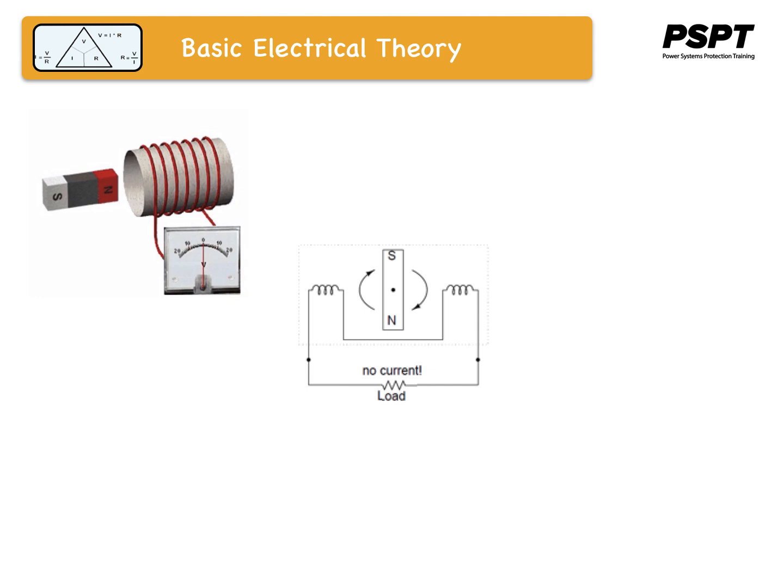If the magnet is in this position as it rotates, there's no current flowing because there's no magnetic flux cutting the coils. But as we turn the magnet, you get a maximum cutting of the magnetic flux in the case that the magnet is horizontal. So you'll get a push and a pull of a current in one direction. And as it rotates, it will go back to zero again. And as it rotates further, you'll get a push and pull in the other direction.